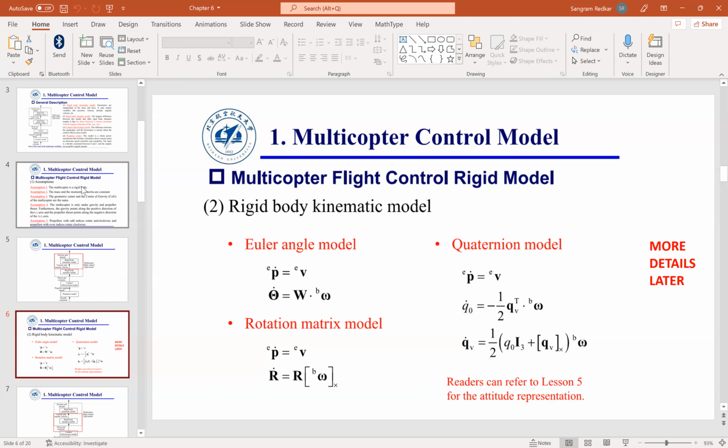the IMU, which is mounted inside, which is 3-axis accelerometer, 3-axis gyroscope, is also aligned like this because it's strapped down. It is glued to the frame, which means the rate and velocities and positions that are measured by the IMU are going to be inside the aircraft body reference frame that somehow I need to transfer back to the Earth center, Earth fixed frame, so I know how far this UAV has traveled or what is its current orientation. Everyone understood this?